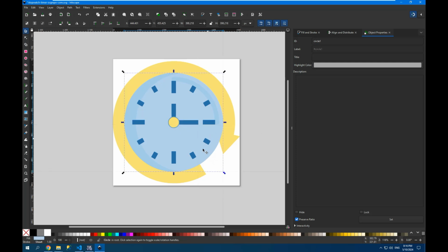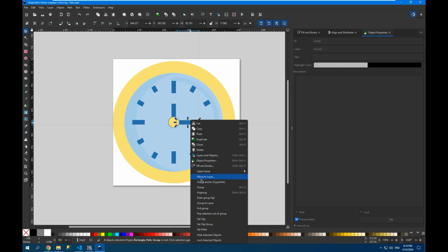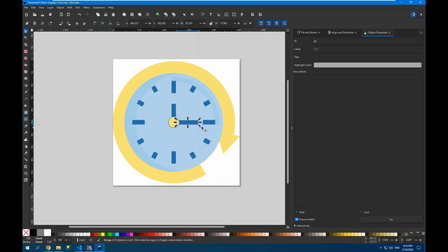How to do it? For convenience, press the Shift key and select our group of objects. To check that all the objects are in the selected area, we can drag and drop them, and they are dragged all together. Now right-click the mouse button and do a grouping. In this way, all three objects are combined into a group.